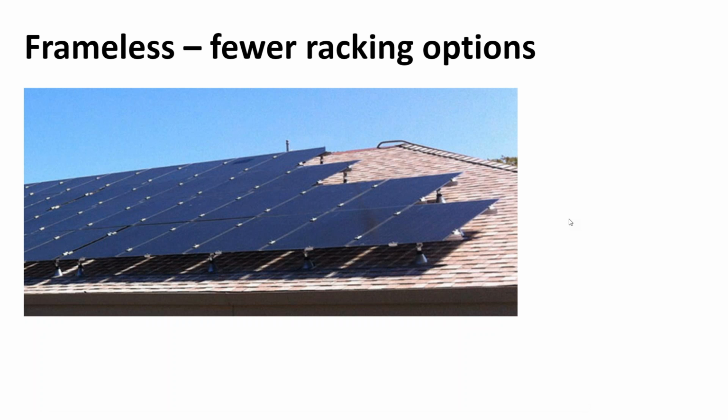But you might find a reason why you need them. I mean, you can get a frameless solar array, and then there's no conductive edges. The ones that I've seen have been intended for purposes that have never really made it to market. So we were looking at frameless panels for a utility scale project back in 2014, and the idea was that they could just be glued directly to the racking system, and not only do you save a couple pennies not having the frame, but also improve your installation time.